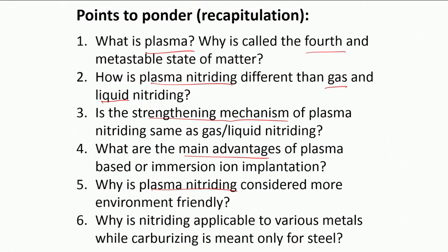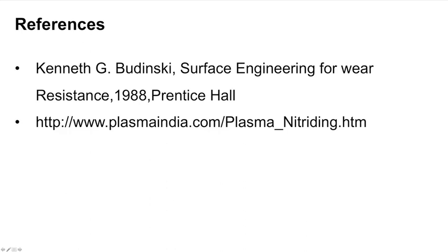And what we should also appreciate is that nitriding as a whole is a process which is applicable not only to steel but to various other ferrous or non-ferrous metals, whereas carburizing is primarily meant for steel. So with this we come to the close of the process description of carburizing and nitriding treatments, and now what remains is to take a quick look at the overall scope of heat treatment, why these are necessary after these kinds of primarily carburizing treatments and sometimes also nitriding treatments.